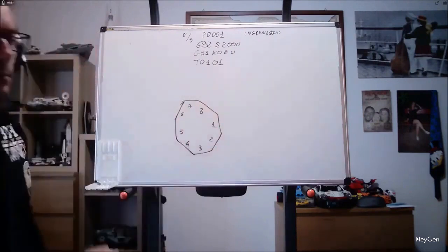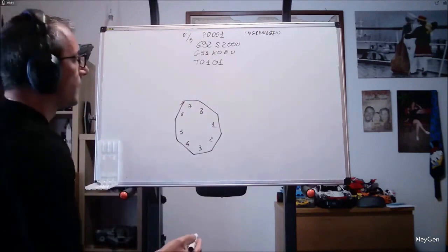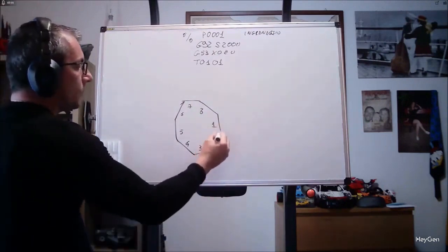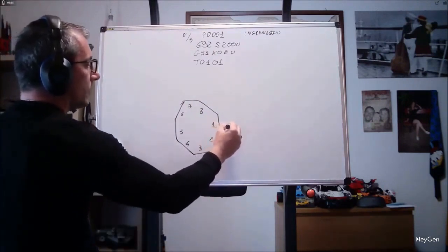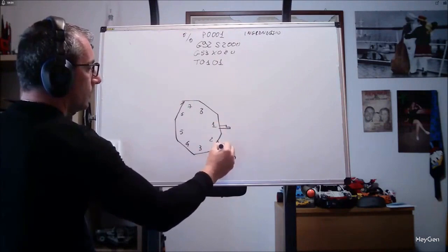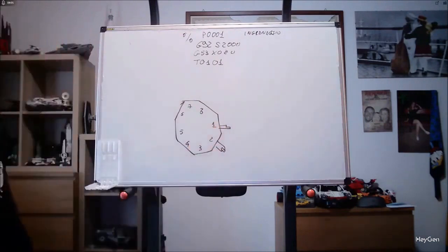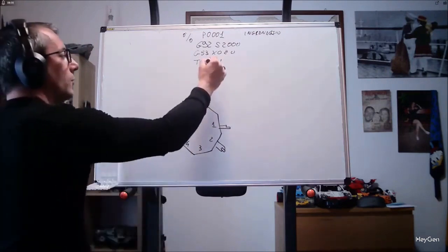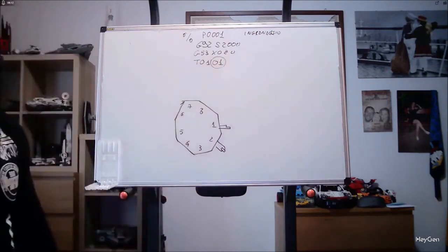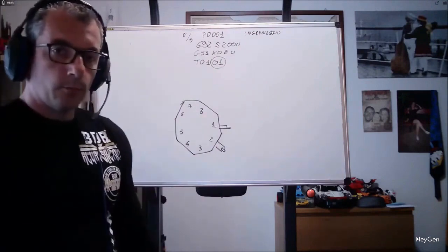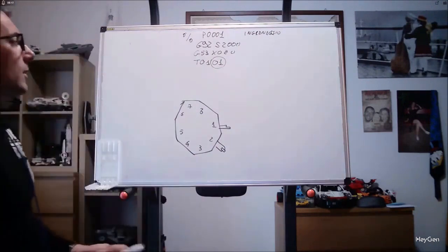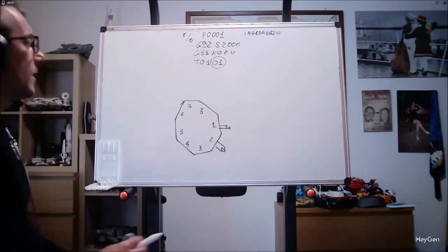You will mount a series of tools on these positions. So if you need a tool for grooving, rather than a tool for external turning, you will call T1 or T2, 01 or 02, meaning the offset, for this little number here. We will talk more about the offset later, just so you know. Because at the beginning of the program, you must call the turret.